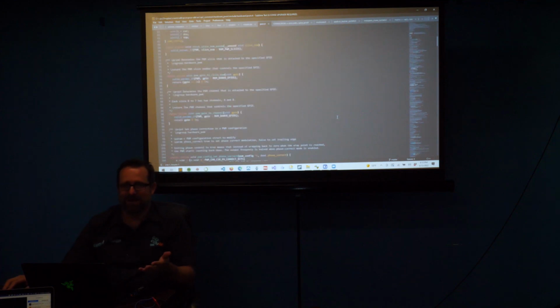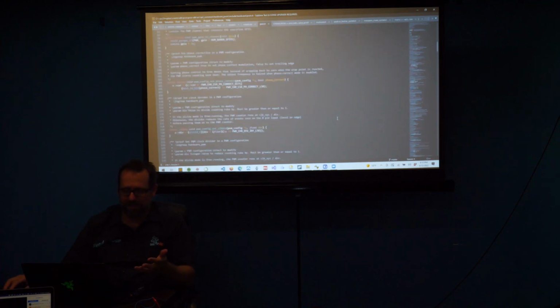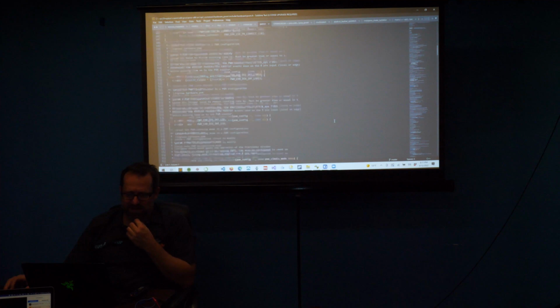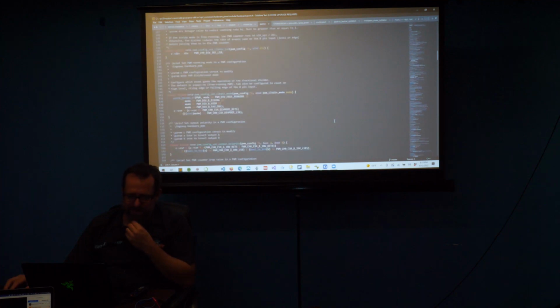What's nice about the SDK is that all the code's there, and if you were a purist and you're going to read and write registers directly from the data sheet, at least there's an example of someone doing it. There are some questions you might have that aren't obvious from the API documentation, like how interrupts work.